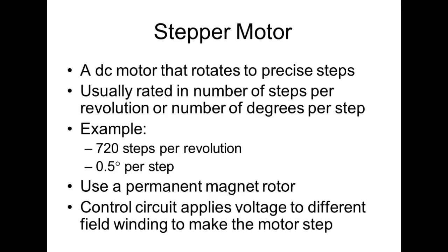So stepping motors are used a lot in 3D printers. It's one of the cheapest ways to do it. But if they ever stall, this open loop, if something happens and they ever stall for some reason, they don't know it. They'll still go 50 steps this way, 40 steps that way. So you got to make sure. And your printer does that every once in a while.